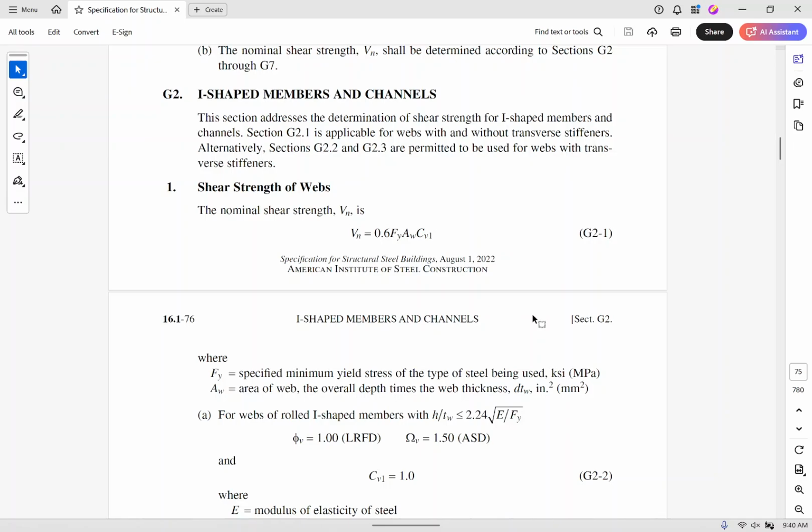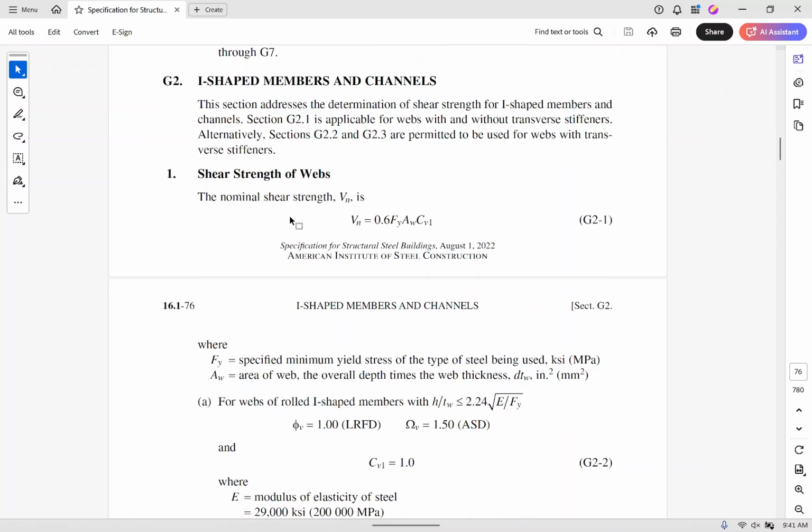actually being yanked on. So really what you have is a situation where you've got a member, member, member, member, and it's almost like a truss. You can treat the plate girder like a truss, and this little band of plate within that panel, which we call a tension field, can still resist load. You have to do that in cases where you have really high shear if you want an optimal design, so we call it tension field action. Those are highly specific cases in steel design. We're not going to worry about that for routine beams and buildings, so we're not going to talk about it here. We're just in shear strength of webs.